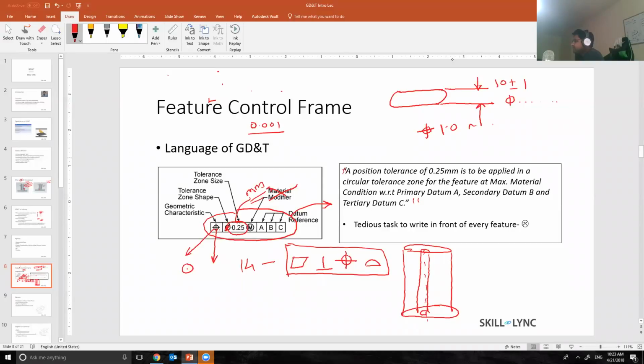So, and then I have another tolerance called out in this direction. So what I'm trying to do is I'm trying to control the slot in X direction and I'm trying to control the slot in Y direction. So diamond pin is nothing but a gauge pin. And what it does is that to simulate a datum feature simulator for this slot over here, I will create a diamond pin. So diamond pin will look something like this.